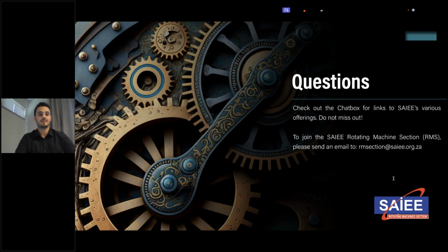I can, but I didn't actually look at connecting it to the grid, so I didn't look at the reactive power. I was just looking at seeing if I could get the torque ripple lower on these electrical machines. So I can't exactly answer that question. Okay. The second part of his question says, did you account for the field copper losses in your WRSG? Yes, I include my core losses and my winding losses.